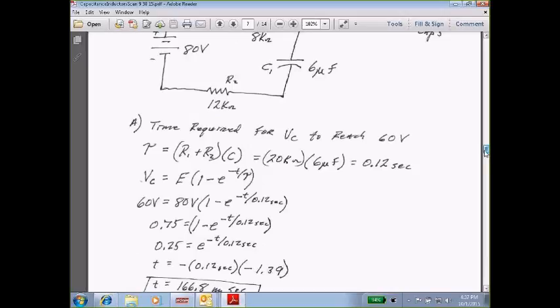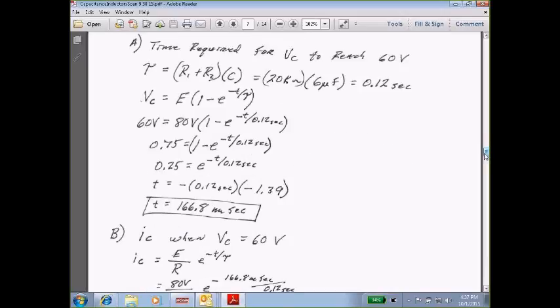And again, I stress with the students that with a capacitor, once it's fully charged, once the voltage has been applied and more than 5 time constants have elapsed, and the cap is fully charged, there's no current flow through the cap, and there is a potential difference in voltage across the terminals of the cap.